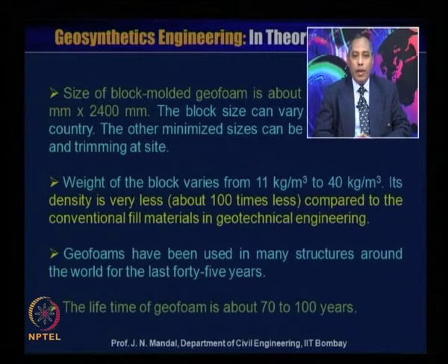Weight of the block varies from 11 kg per meter cube to 40 kg per meter cube. Its density is very low, about 100 times less compared to the conventional fill material in geotechnical engineering.